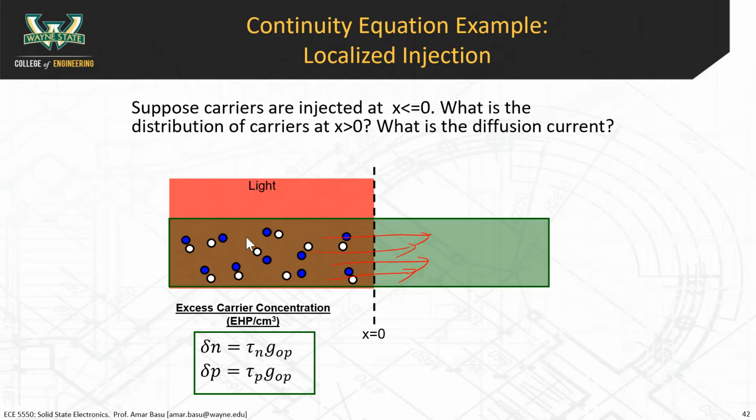But it turns out that when you turn the light off, then it takes longer times for those carriers to decay away. It's a subtle but important point. When you turn the light on, that equilibrium is established very rapidly. Generation, recombination, they establish a very quick equilibrium. So the excess carrier concentration goes up almost immediately. But when you turn the light off, now you have that concept of the minority carrier lifetime, where there's an exponential decay over time.